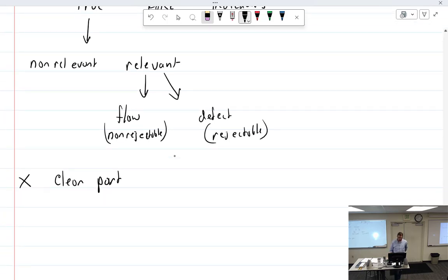Clean the part, you use a penetrant, apply anti-corrosion, preserve the part. We could really add in one more step, and that would be paperwork, because you do need to document what you did. I learned this back in my ambulance driving days. They said, if you don't write it down, you didn't do it, which worked to my favor a lot.